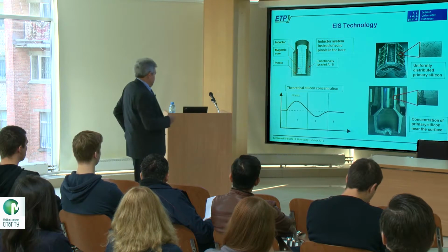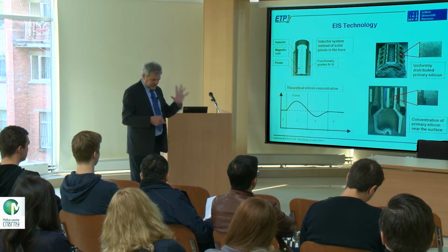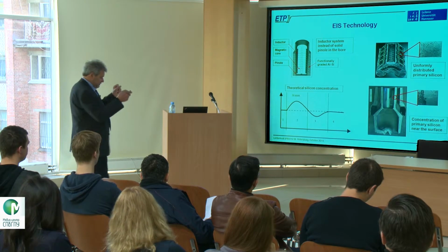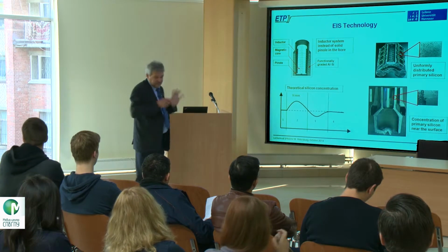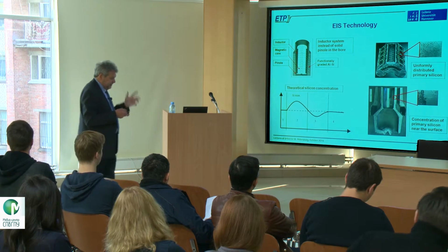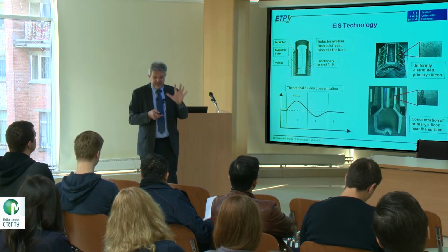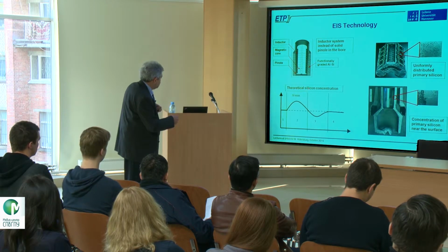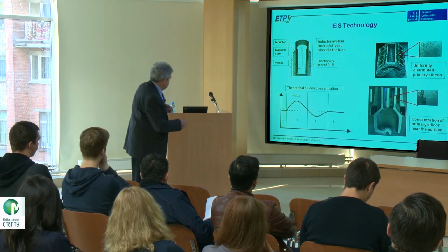There were some theoretical investigations before. They show that if you use this during the solidification phase, you melt the aluminium material, then cast it into the casting mold where you have the shape inside. If during solidification you let electromagnetic forces treat this solidification, then you get this shape of the silicon concentration. Here is the surface on the left side.